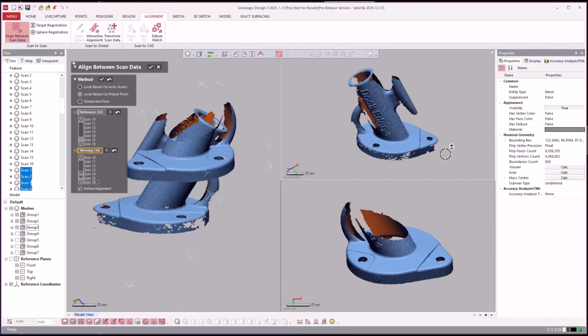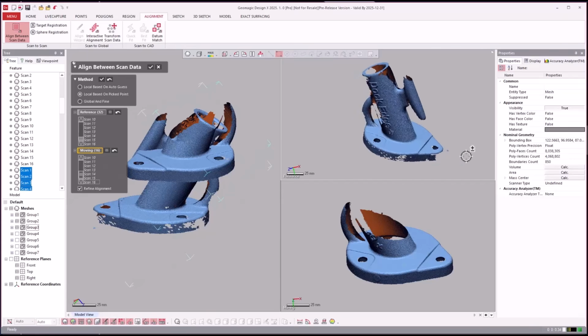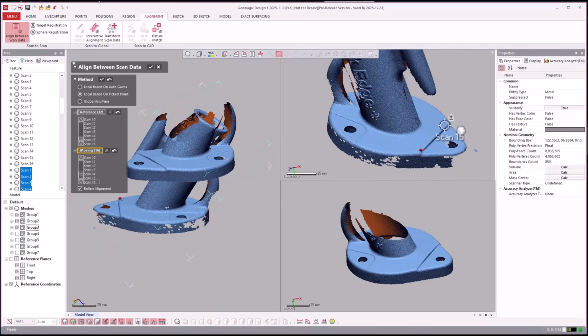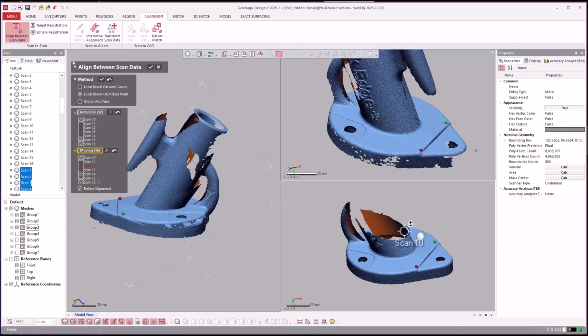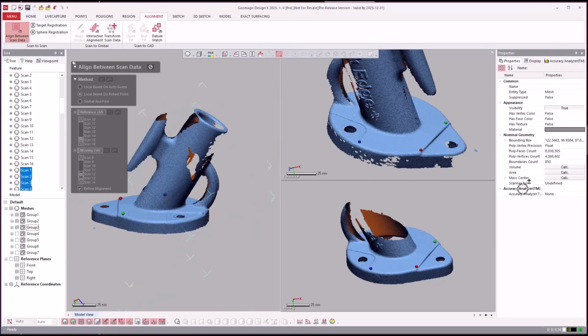And it helps to select points that are spread out and not directly in line. So if I do something along these lines, if I grab these two, I want to select something like over here. And you'll notice I'm not doing them perfectly, like zooming way in. You can, but I'm just getting close, because we're then doing a very basic global find in the background between the two groups of scans. So you just need the points close together.